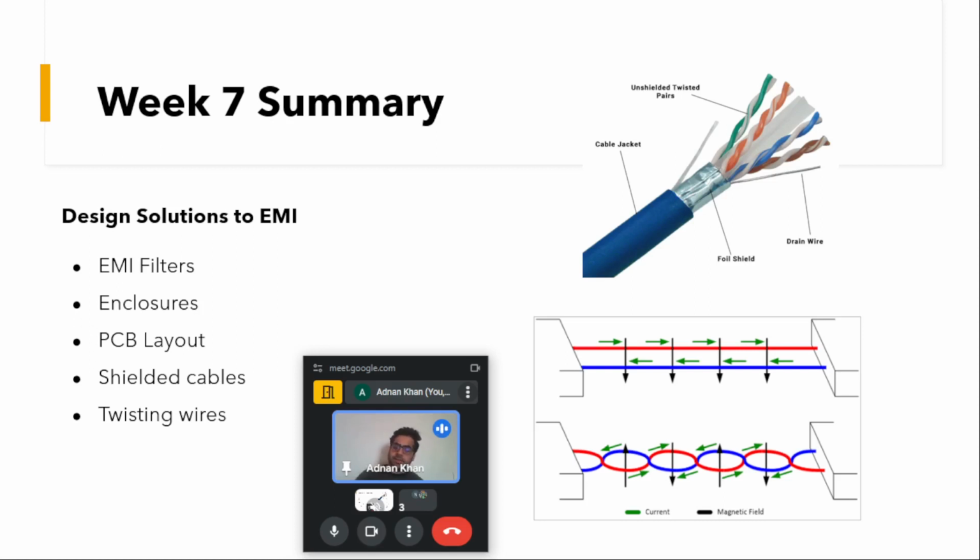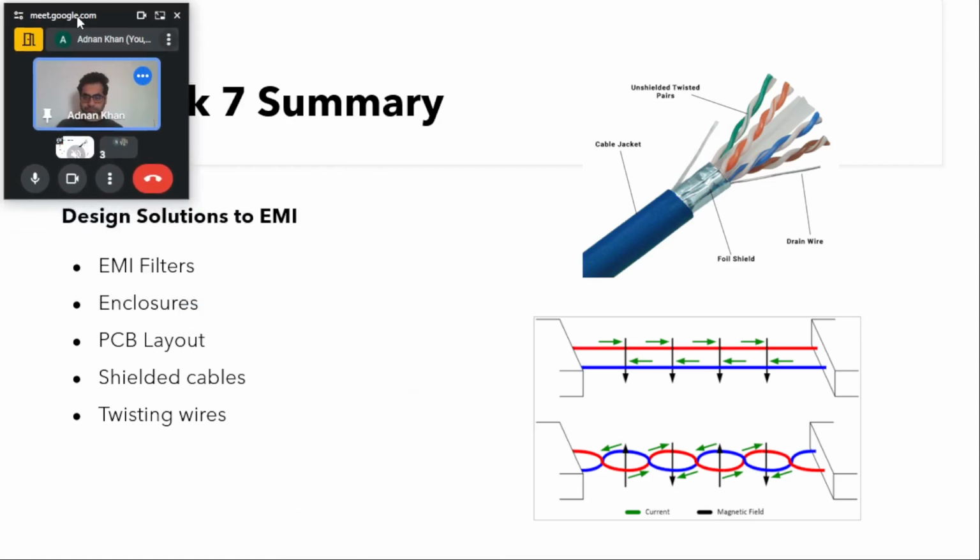And the second thing is the enclosure. Like I told you, we want to enclose our converter, so that, like you might have read about the Faraday cage and so on, we have a metal enclosure. If EMI is being generated by some other converter or part, it may get propagated to a particular part.